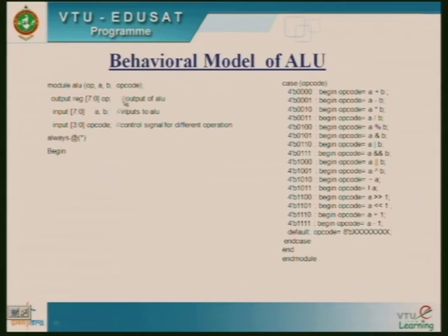Note that you can write comments by giving a double slash here. // will represent a comment line. The line always ends with a semicolon. Now I am using always @ either of these conditions, begin. I am using a case statement with opcode. If this opcode changes, based on this my output will be redirected. The 4 represents a 4-variable: we have 4 selection lines.